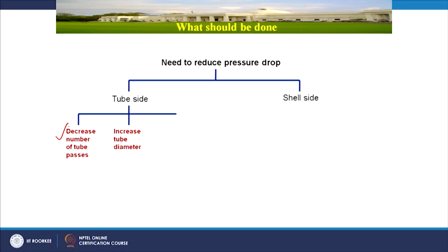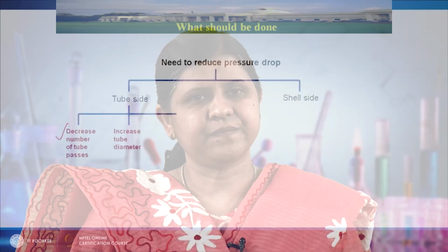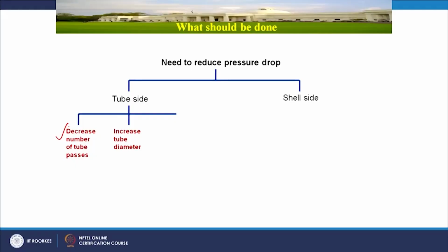So, if you are changing the diameter, the heat transfer coefficient will not differ significantly. Okay. But all these changes like changing the diameter etc., you can make slight change in calculations. But when you are changing these things like diameter of the tube, the pressure drop and heat transfer coefficient change will be very less. So, if less variation is required, then only you should proceed for that, otherwise passes will be the better option. I hope I am clear.